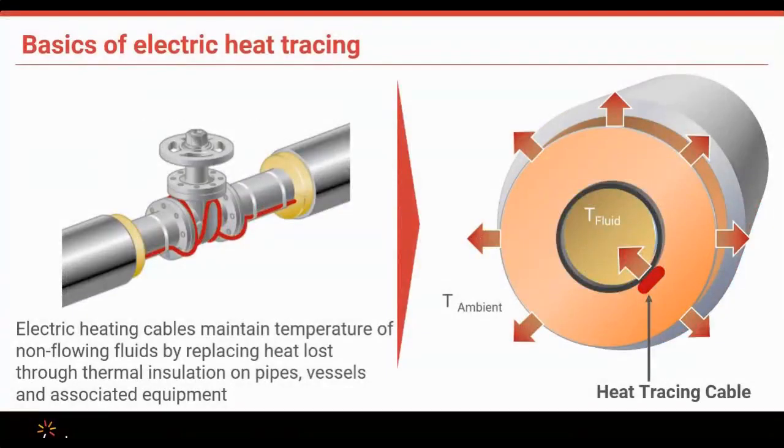So today, we're going to talk really the basics on what heat tracing is and how you can look at a project and be a little bit more knowledgeable on what you need to get started. So the basics is you're putting an electric cable on a pipe in this application. That pipe might be for freeze protection, or it also might be for flow maintenance. Depending on what you're looking at, those are the 2 things to consider.